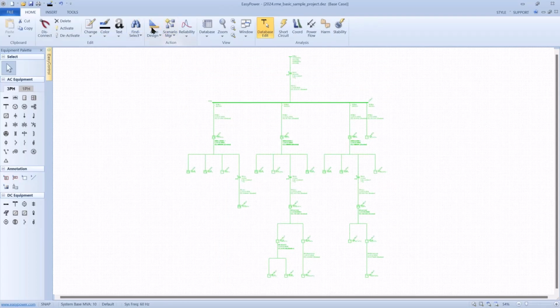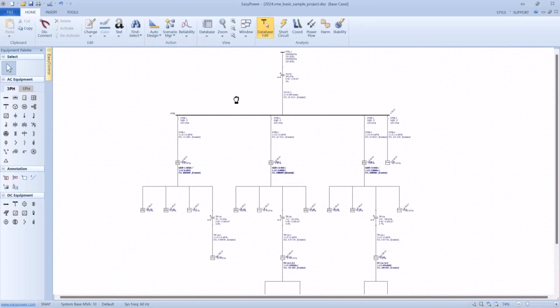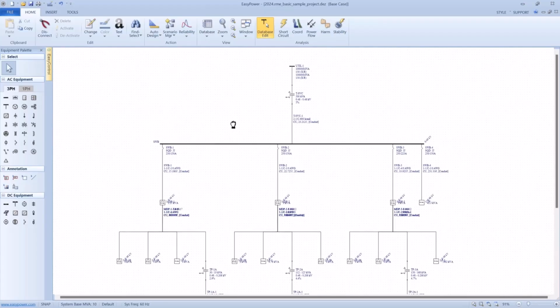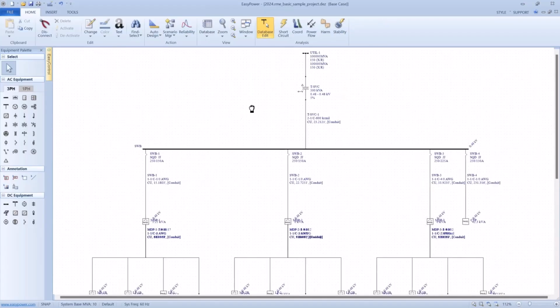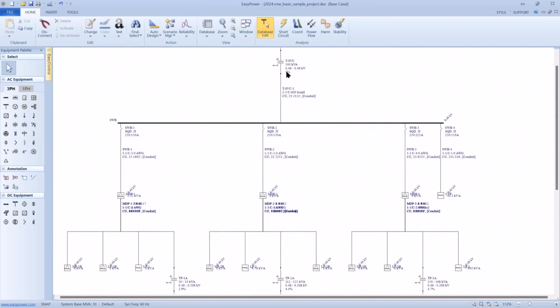Now, again, what I'm expecting is a selection of Square D parts based upon a decision tree that I've established in the device library. And I'll look at that before we're through here. But as I come back to it now, I see my transformer based upon 480 volt to 480 volt requirement is recommending a 5% impedance ratio and a 500 kVA size.